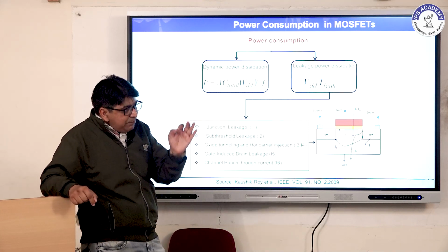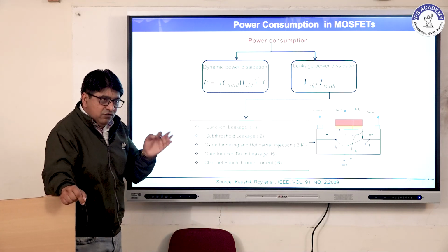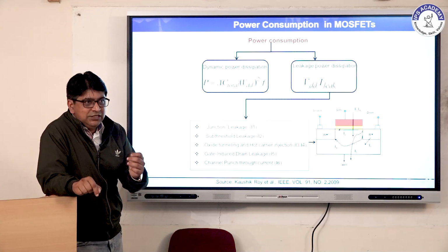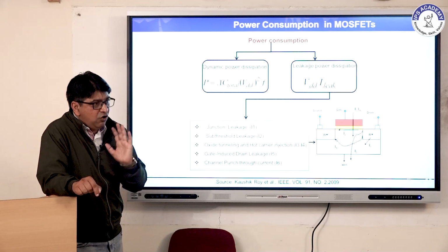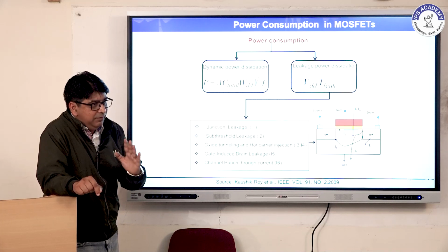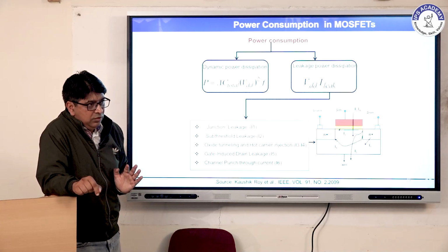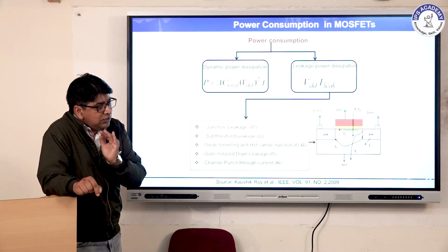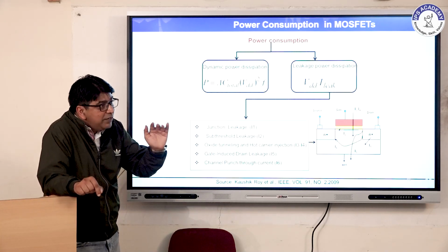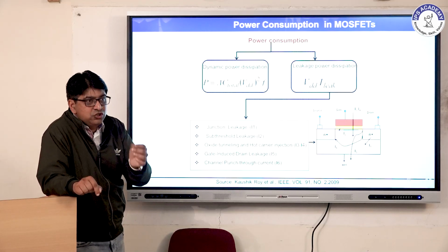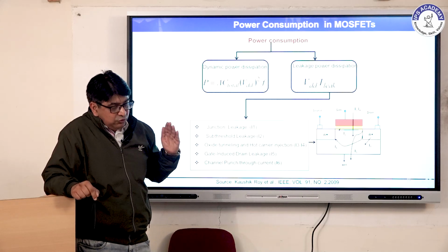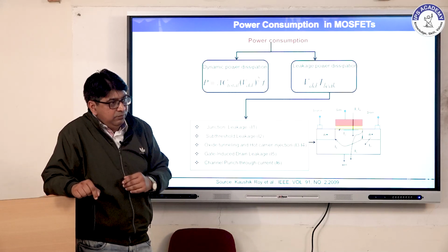The subthreshold swing is the one parameter, as mentioned in the starting. If you want to use the device for digital applications, the subthreshold swing will suggest how effectively the transistor turns on and turns off. If it turns on and off rapidly, the device will be good for you. But as we scale down the transistor size, the subthreshold swing also should scale down to maintain the leakage. If the subthreshold swing is not going to scale down, leakage will start increasing. Subthreshold swing shows one slope.